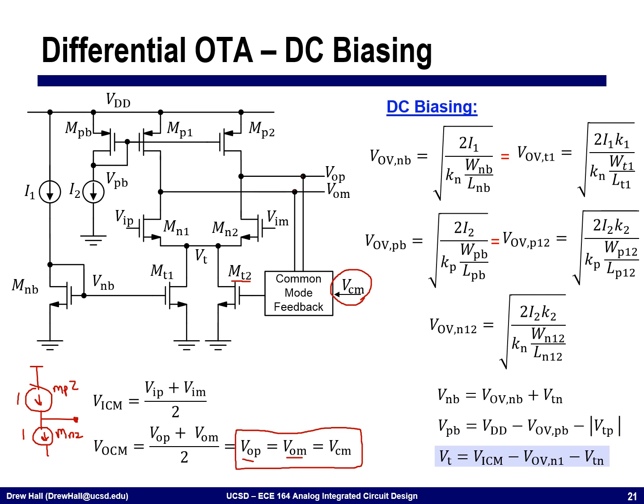We'll talk a little bit about this particular structure, but in reality, it actually looks a lot like this differential amplifier shown here. So it's just going to measure the difference between these two voltages relative to the common mode voltage, and it's going to apply a voltage here that adjusts the amount of current that's flowing through this in order to move up or down these voltages.